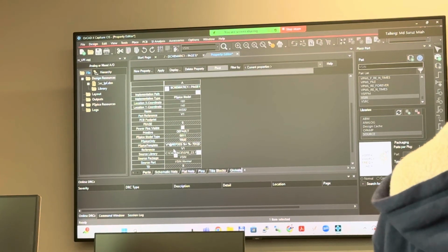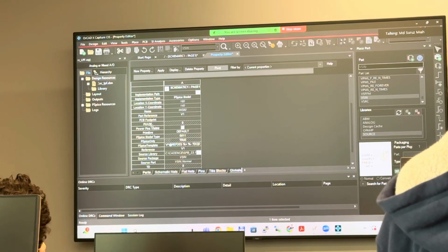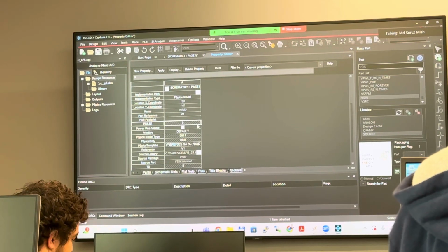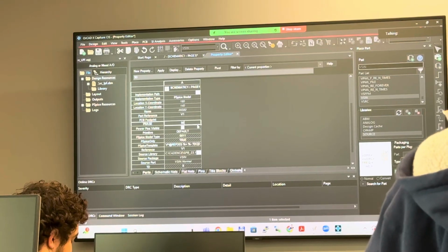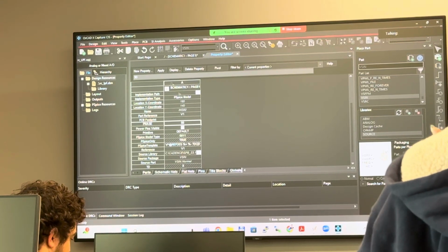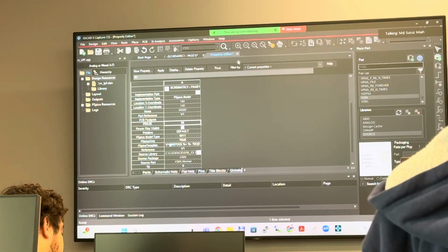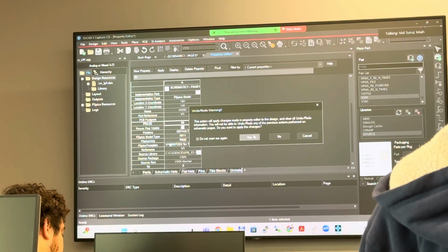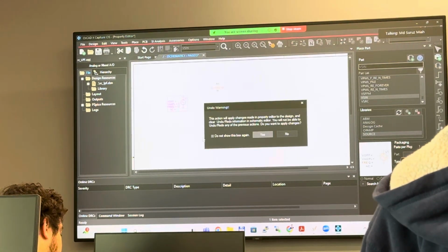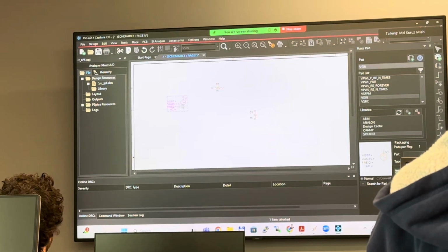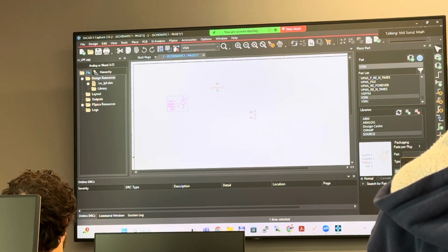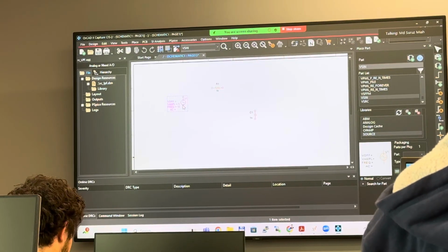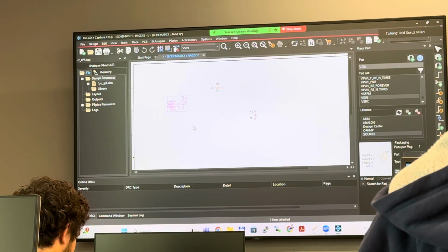Now, do you see phase here, right? Phase is currently 0. Make it 90 degrees. Now, if you simply close the property editor, it will take effect right here. So it is now a cosine signal.